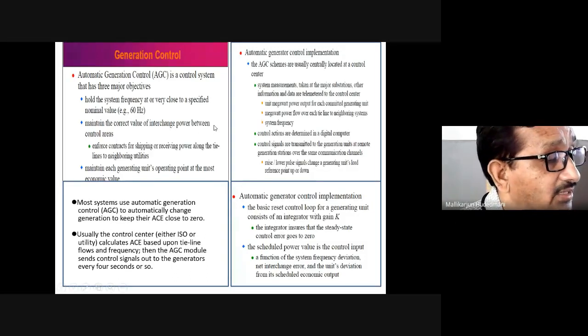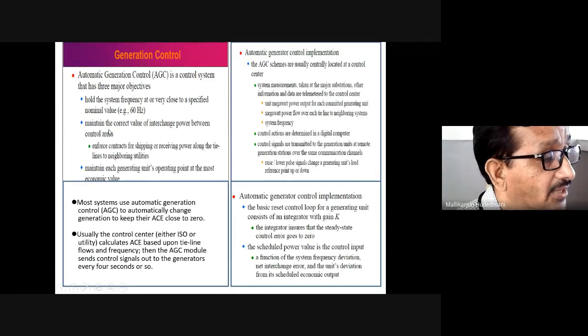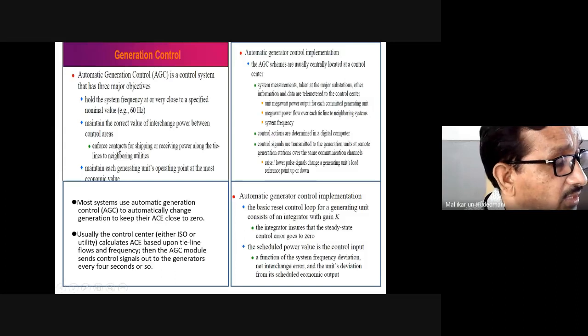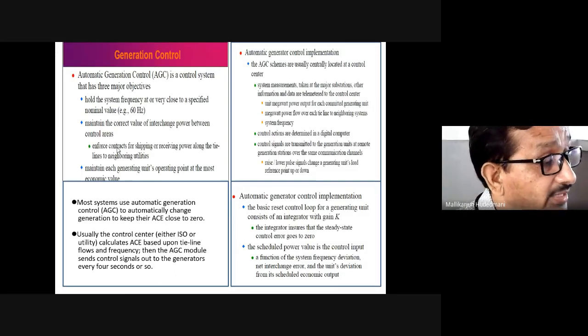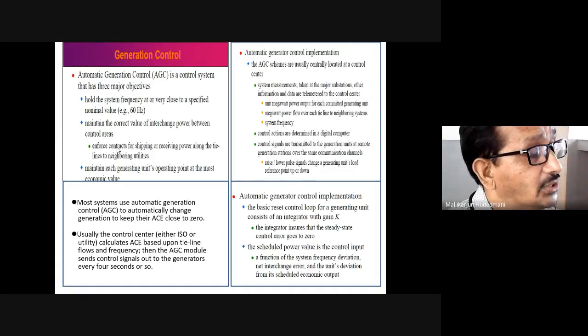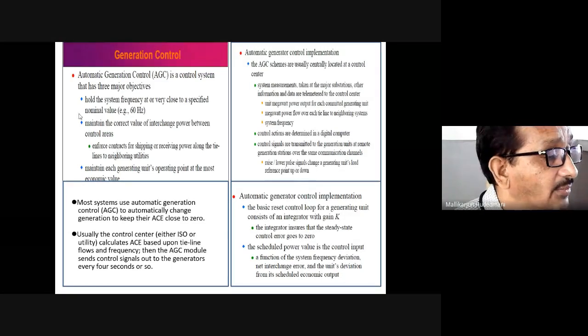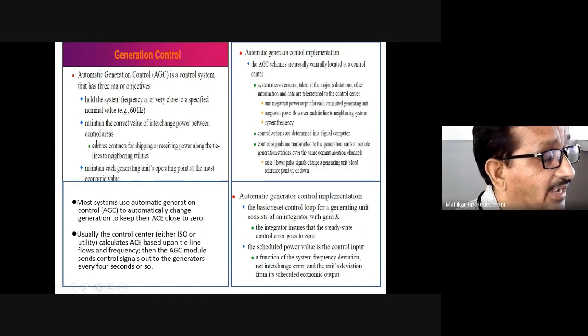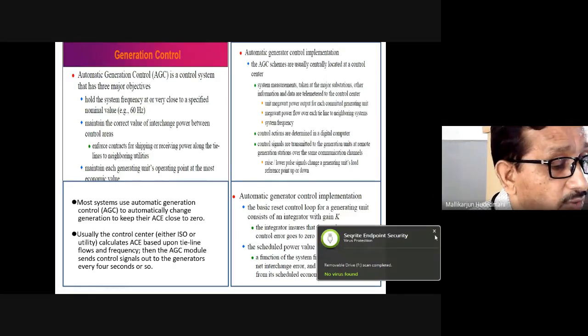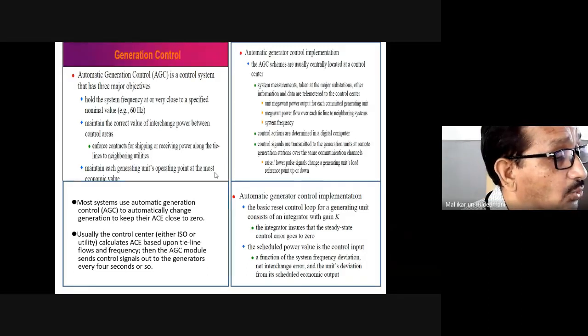With that requirement, the first keyword we learn today is control area. A control area is the geographical periphery of a power system. It can be a power system, or part of a power system, up to its encompassing boundaries. A control signal from a center or a common point executes, reaches and acts upon it. That we call a control area. Like that, a generating station is a control area. Another generating station is a control area. A generating station along with the load and transmission grid can be a control area.